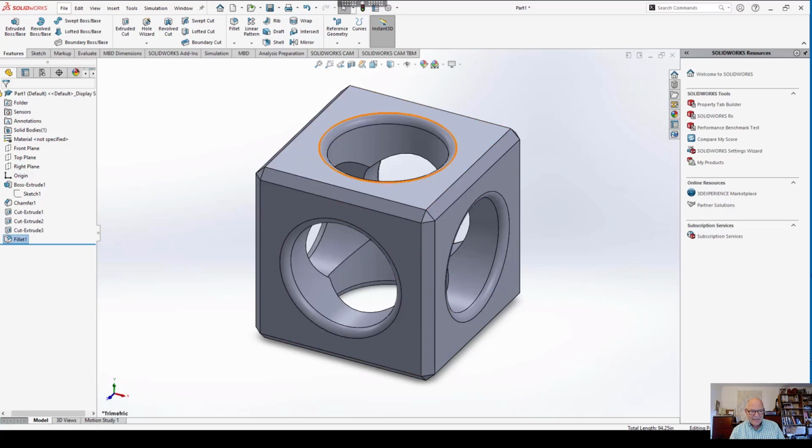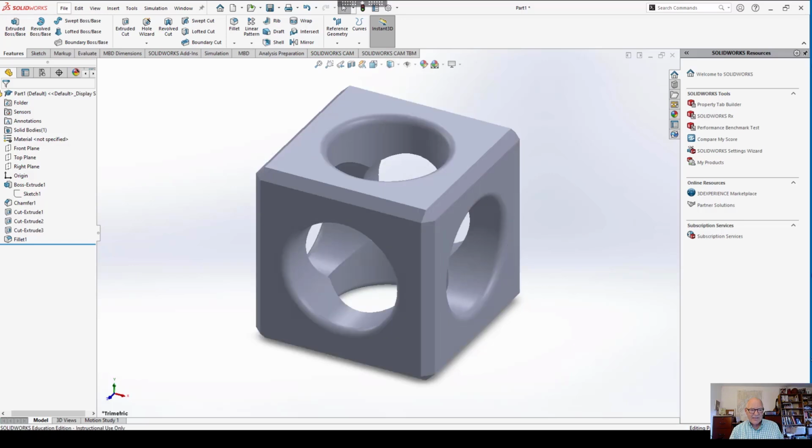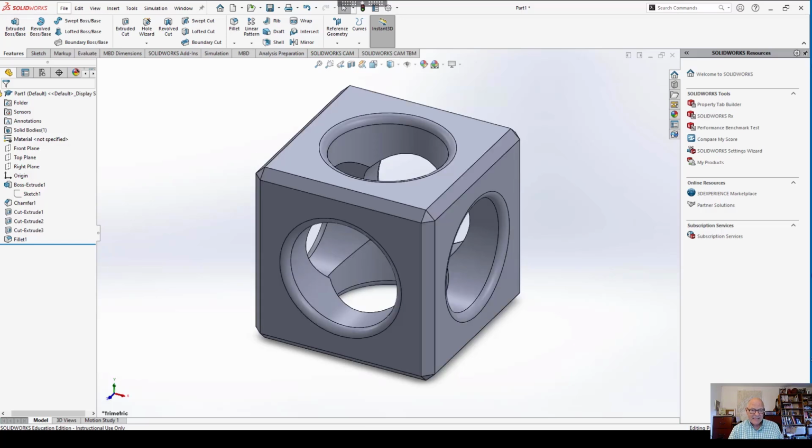Now these edges, these lines right here, show the tangency, and that's just because computers recognize that surface is different from this one, so it puts an edge. If you were to come up here and say don't show the edges, it would look like that. So you have edges right here, sharp edges, because that's a flat surface. Here those tangencies don't show up because you wouldn't actually see them. Some people like working like this, I like the view to look like this, just because it's easier to see what I'm doing.